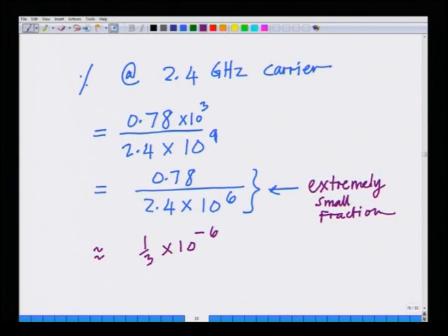That is what this seems to imply. So, carrier synchronization is a very, very critical aspect of any OFDM system, because if the carriers at the transmitter and the receiver are not synchronized, then we have serious intercarrier interference, which results in a tremendous decrease in the SINR at the receiver. Okay.